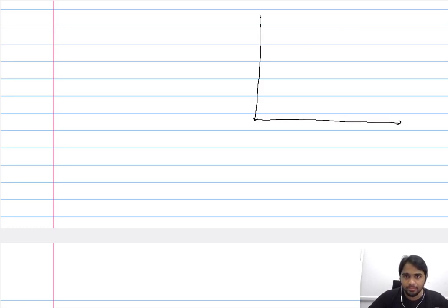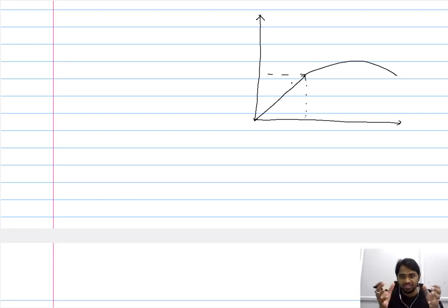Now we have seen there are different properties that one can calculate from the stress strain curve. So let us again stick with the engineering stress strain curve. So let us consider a representative one. It comprises a linear region and a non-linear region. The linear region, this region here, is where the material experiences elastic deformation, and the slope of this region we refer to as the modulus of elasticity.